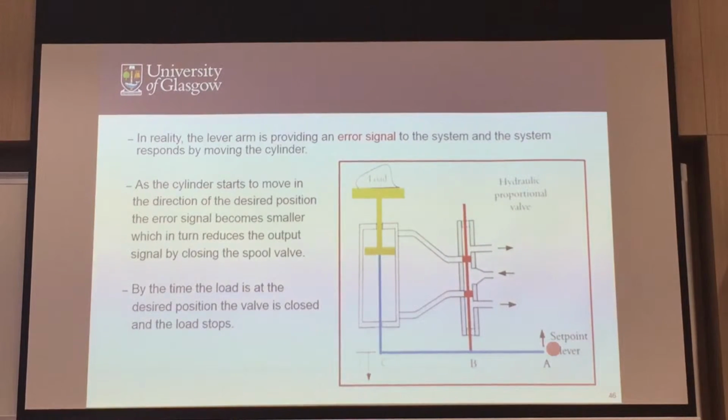So I'll let you watch this animation twice. So the first one is that you have the actuation, you lift it up. So you can see that the spool starts to move upward. So when the spool starts to move upward, you'll find that this top part over here will get energized, and hence the load will be pushed downward.